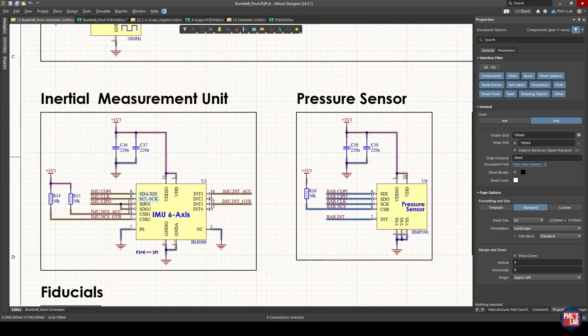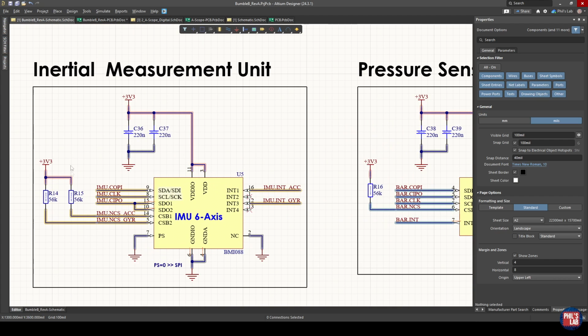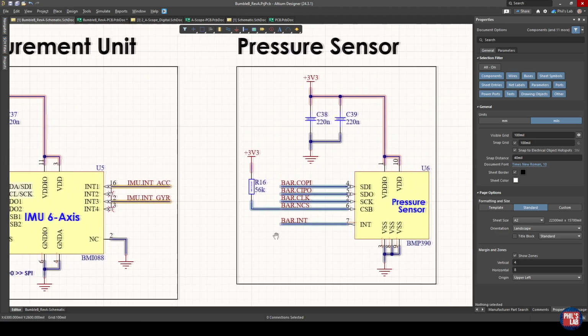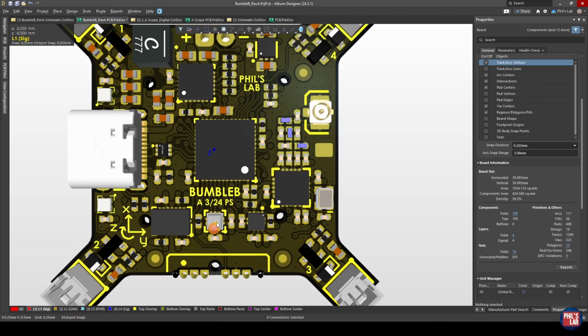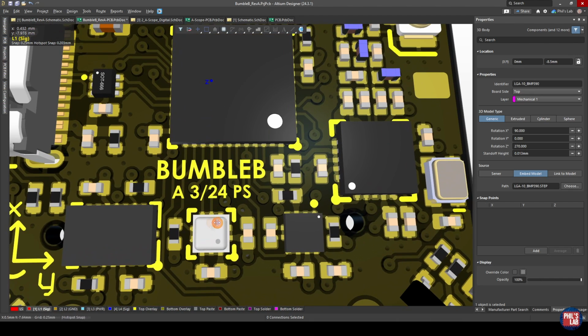What I do, however, have is, as we saw before, separate chip select pull-ups to the 3.3 volt logic at 56k, and that's just reusing values I had before. But other than that, I don't have any pull-up resistors. For routing and layout, I didn't do anything special, so to speak. For example, the controller's in the center, and then I have an SPI connected up and between this peripheral, which is the Bosch BMP390 pressure sensor.